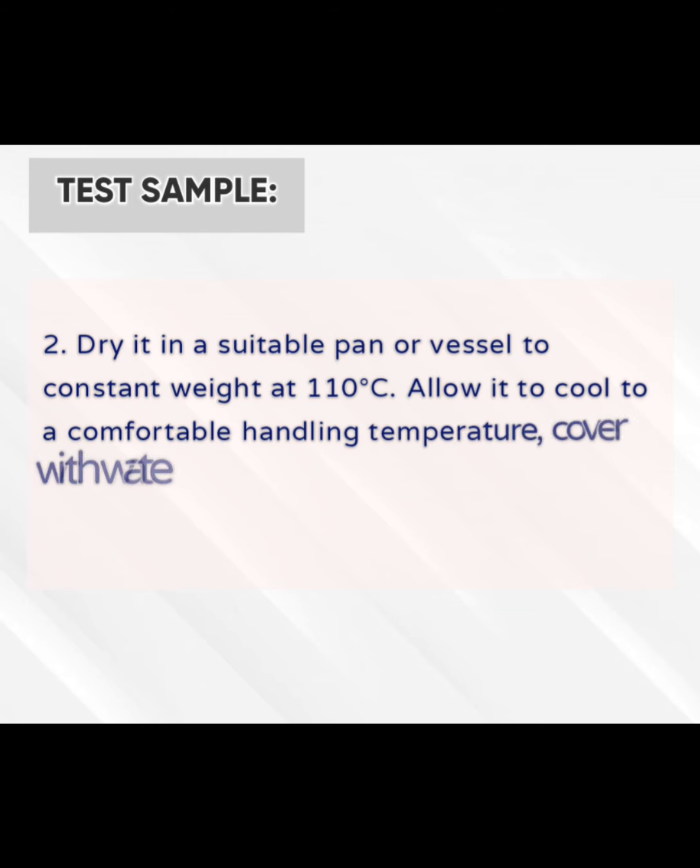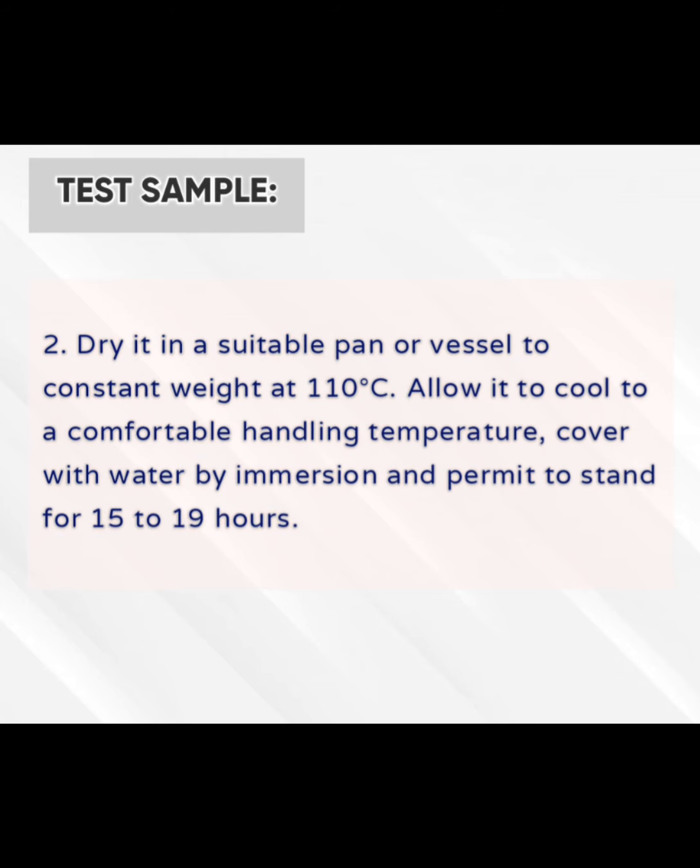Number 2 is dry it in a suitable pan or vessel to constant weight at 110 degrees Celsius. Allow it to cool to a comfortable handling temperature. Cover with water by immersion and permit to stand for 15 to 19 hours.